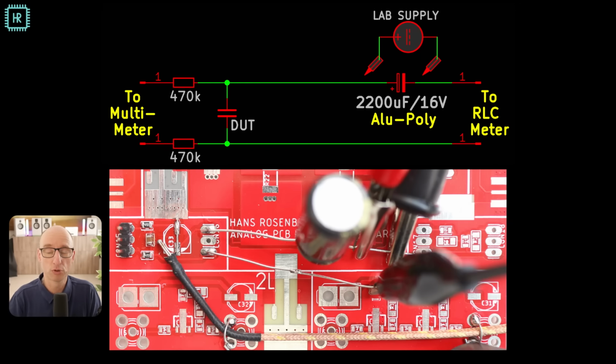The multimeter is normally not connected. When measuring, however, you have to be careful. A multimeter often has an input resistance of 10 mega ohm. So with the two 470K resistors, that creates a voltage divider, causing you to measure a lower bias voltage. You have to compensate for that.